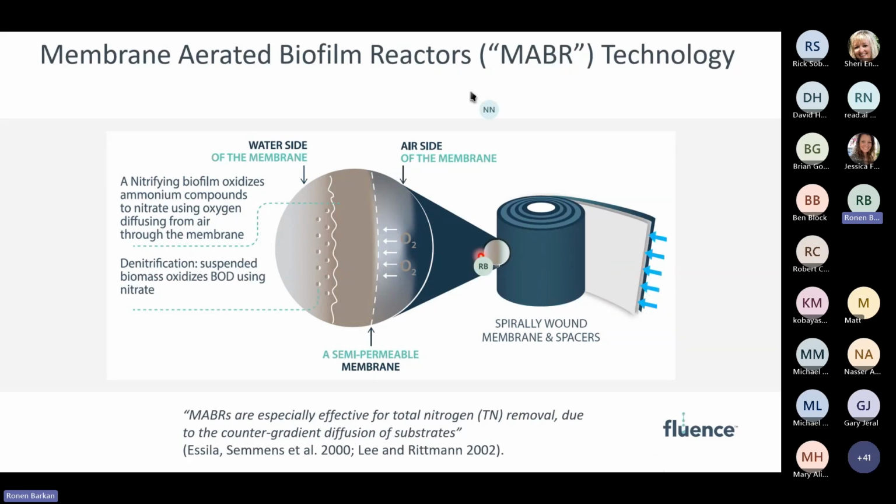So essentially what is happening, and at this time, the white dashed line right here represents our semi-permeable membrane. As I explained before, we're pushing air into the sleeve, and only oxygen is diffused perpendicular to the direction that we're pushing the air, through the semi-permeable membrane into the wastewater. Adjacent to the semi-permeable membrane from the wastewater side, that is where we have the bacteria that love oxygen the most, because this is where oxygen comes from.